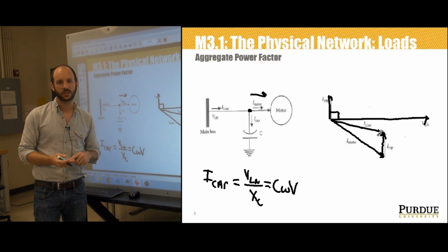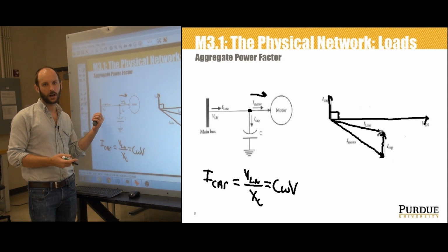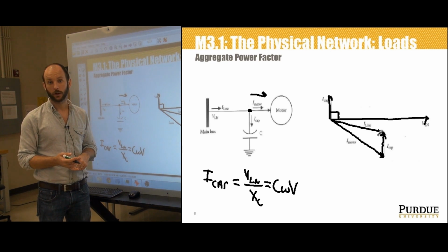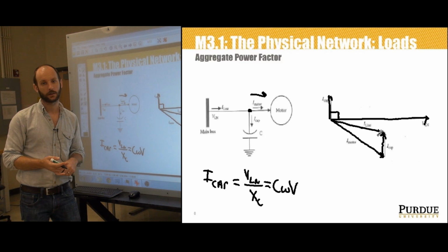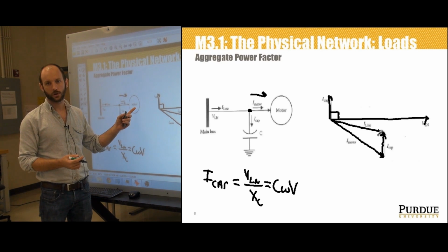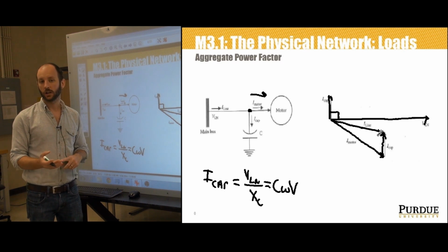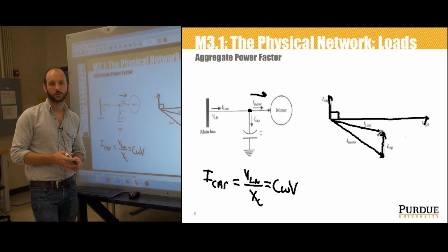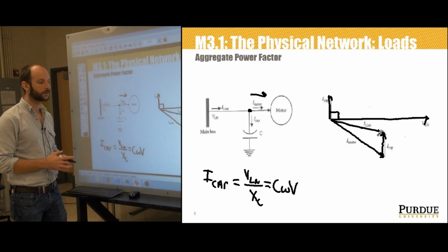This is going to reduce the kVA demand from the line and therefore the monthly charge of the utility bill for the customers who are subject to a kVA demand. The energy charge that's getting charged to the motor in kilowatt hours is going to remain the same, except maybe for a small reduction due to reduced I squared R losses.